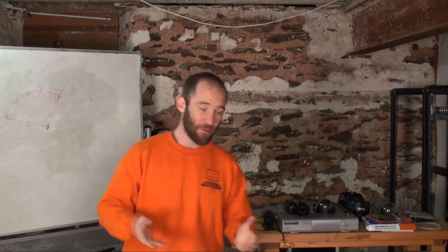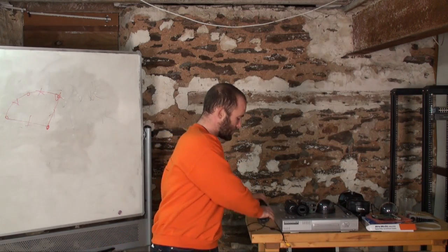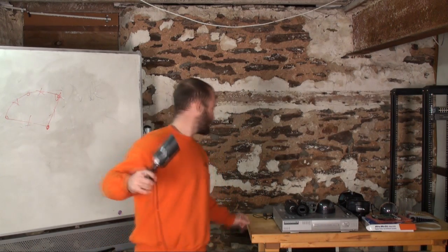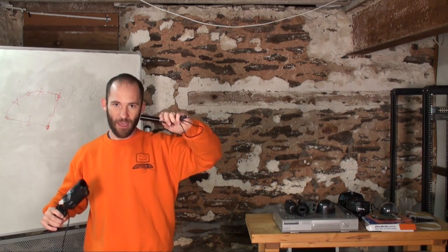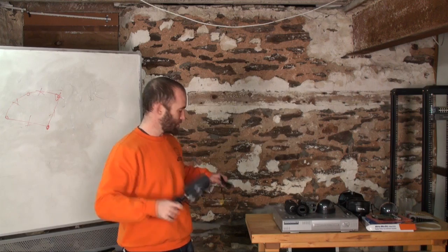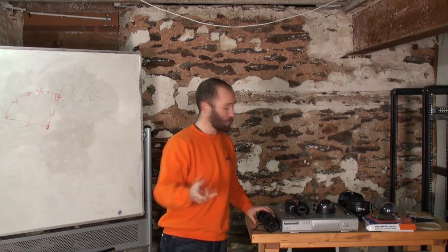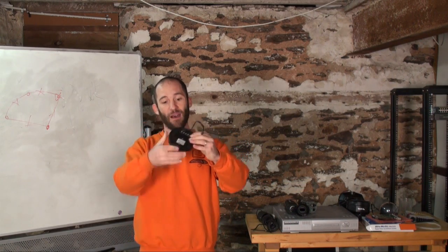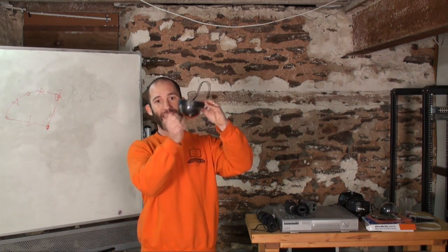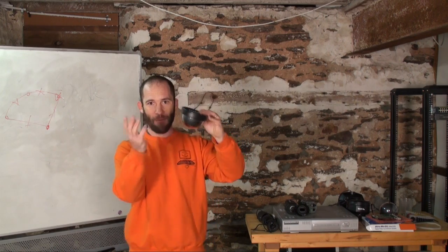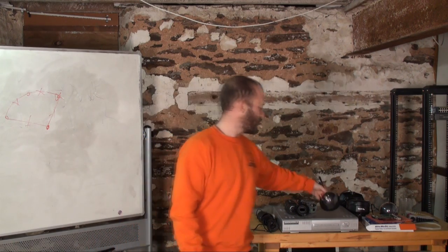We then talked about types of cameras. We've got the bullet camera. This is an external bullet camera. You've got an internal bullet camera. These are very easy to install, but if somebody knocks them and moves them to a different direction, obviously you're not watching what you should be watching. This is a dome camera. A little more difficult to install, but it has a dome on it, so people can't tamper with the camera itself.